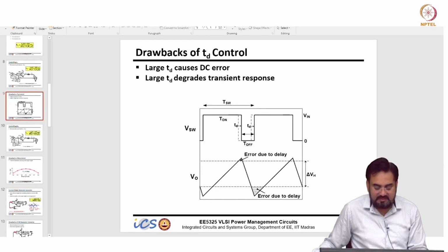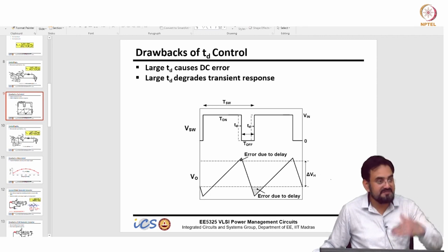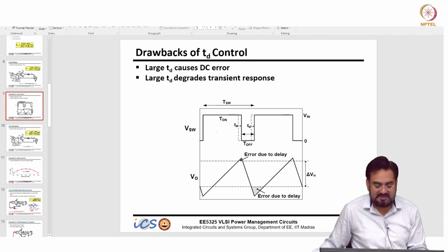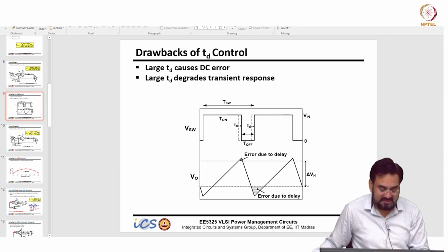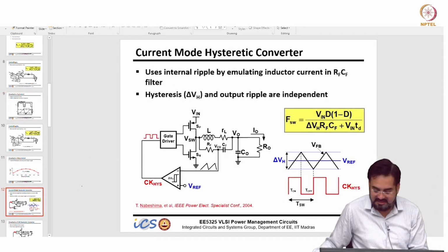So, this is happening due to delay, and you can see this is non 50% duty cycle and this is much larger compared to this. So, average will be shifted down. If you do the same thing at lower duty cycle, much lower than 50%, then you will see this component will be more compared to this, and this is already given in my thesis. If you look at the same chapter, this is given, and how you calculate those frequency and everything is given.